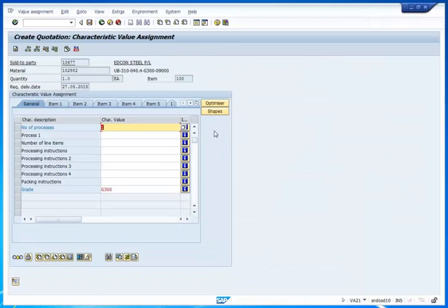Once we're in the processing configuration screen, there's a couple of different things we need to specify. In the General tab, which is where the default screen begins, we need to tell the system how many different processes we're going to have. A process is something that we're doing to it. So process 1 may be cutting, process 2 might be drilling, process 3 might be galvanizing or painting or something along those lines. For this particular example, let's do 2 processes, and you can see the system now opens up and gives us 2 options so we can specify each of the processes.